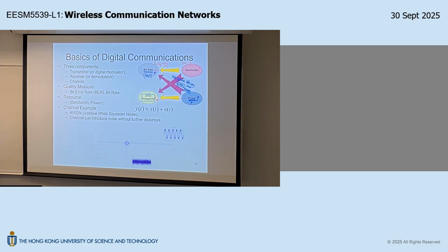If you look at this output signal, so this is the output signal, x(t). If you look at the spectrum of this output signal with clipping, the sideband spectrum may have a regrowth after clipping, okay? So it could happen that if you ignore this clipping issue, your baseband output will satisfy the power mask, but your power amplifier output will violate the power mask, okay? You will have something like this. So this is called spectral regrowth. Okay? Due to clipping.